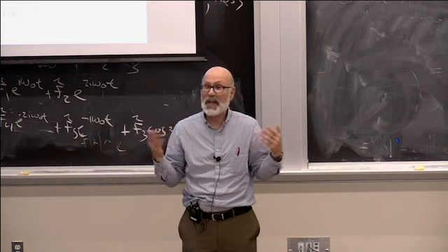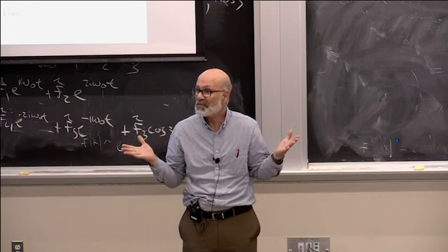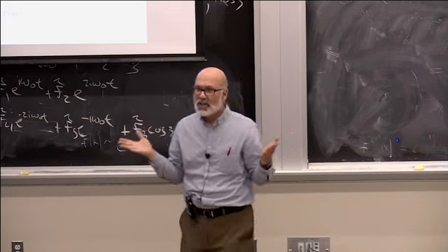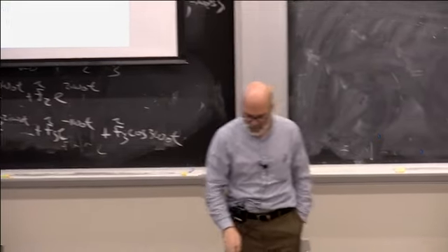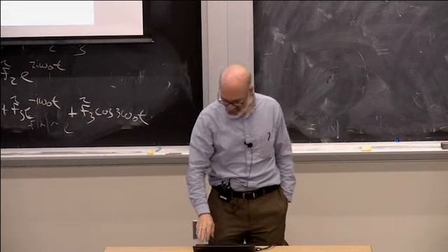And if they don't make it, sorry, 120-second cycle, 100 seconds of red. So that's a situation where a green extension would be valuable in all these cases, but it's especially valuable when there's a really long red time. So I'm glad you mentioned D Street. I'll be talking about D Street.